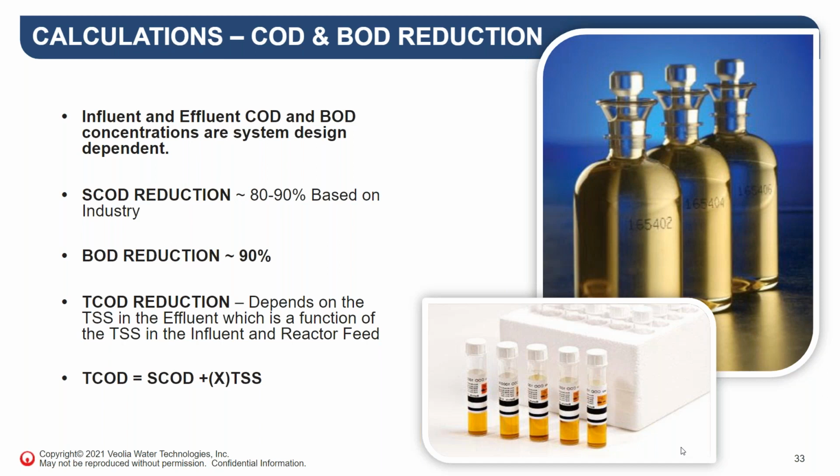Because you got to remember that the total COD is equal to the soluble COD plus some number X times the TSS. And that X is a function of the type of suspended solids that we're talking about. Now, there's exceptions to this. And one of them I see is in the yeast industry.